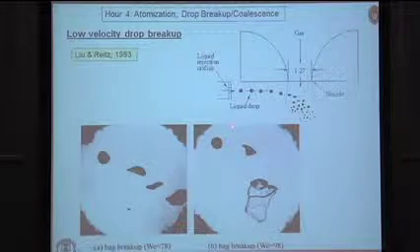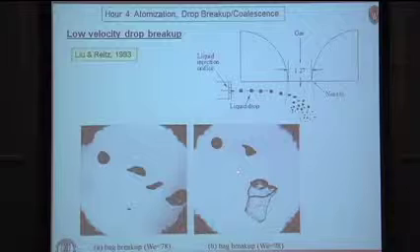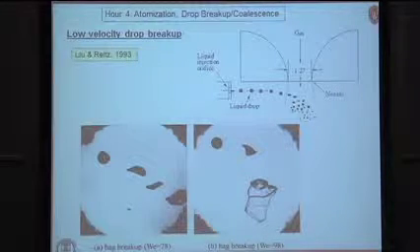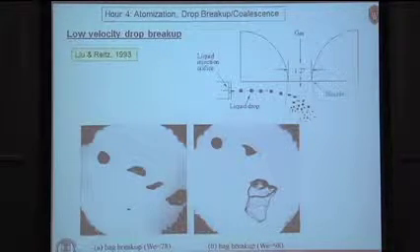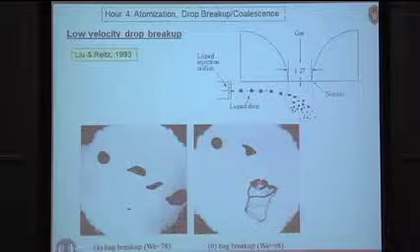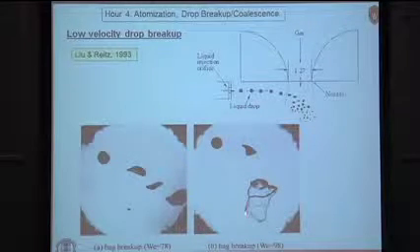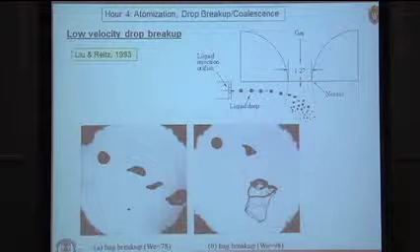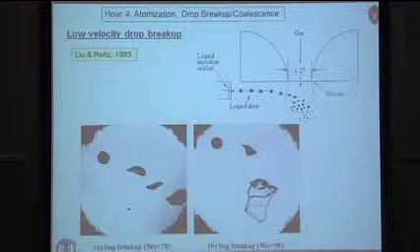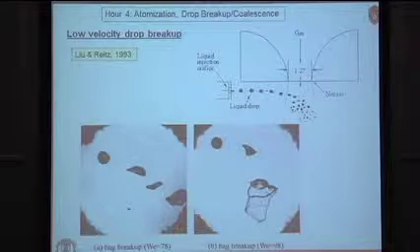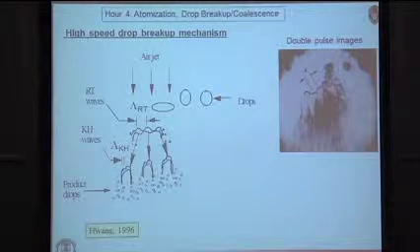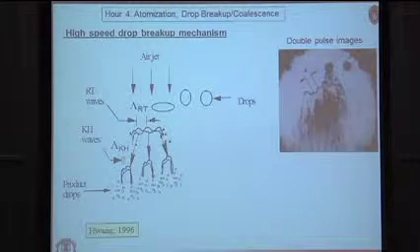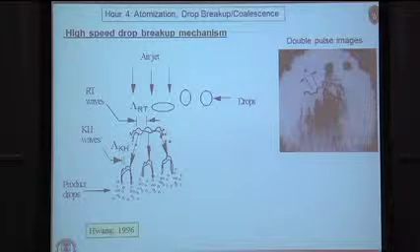As you increase the velocity of the gas, you're increasing the dynamic pressure. The droplet flattens more, and in fact, it can turn inside out and create this so-called bag breakup. So you get this thin membrane that forms around, like a donut, or it's inside the donut. Okay, so that's what happens at low jet velocities, or gas velocities.